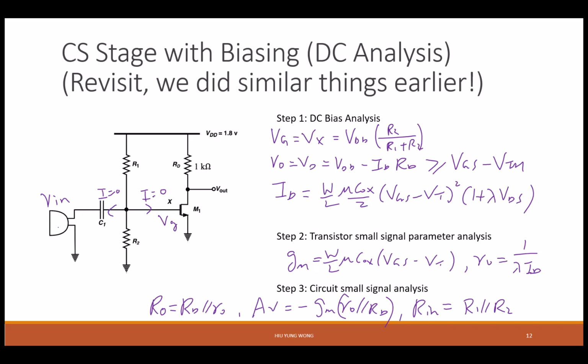Since you asked, why don't we just play with this together? You need to think about how you can map this circuit to this circuit, right? The first thing you say is, I want to treat this whole thing as a resistor, RS. Then I can plug into this equation. But then what is this RS? This RS is no longer R02, right?